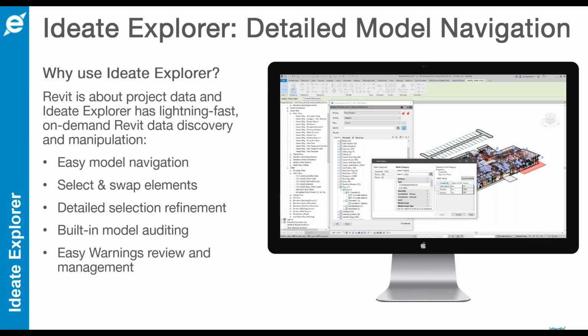But furthermore, we can get in and get really under the hood with our selection. I can take a selection of elements and refine that selection based on a long list of parameters. I want to find some of my ductwork elbows that are 45 degrees or less. I can do that with a product like Ideate Explorer. I want to find all these elements that are hosted on level 1. No problem, we can do that. Help me find in-place families or pinned elements. That's where Explorer can really help you out. We have wonderful built-in model auditing that can help you with those tasks. And also for those of you that need to address warnings, we have a whole warnings management built right into the product.